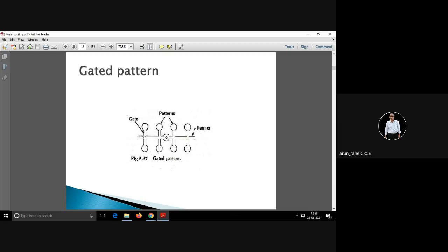And then this gate, runner, screw, runner again. You have the primary runner and this is actually a secondary runner. This is the secondary runner, and the gate is between the secondary runner and this spherical piece. Between the two, the gates are there. So screw, primary runner or main runner, then secondary runner or branch runner, and then gate. So this forms the feeding system, and once they are degated, it goes for remelting.